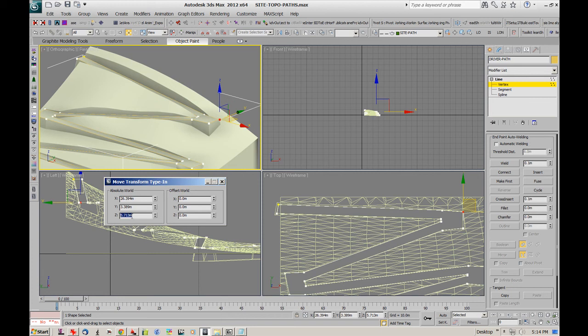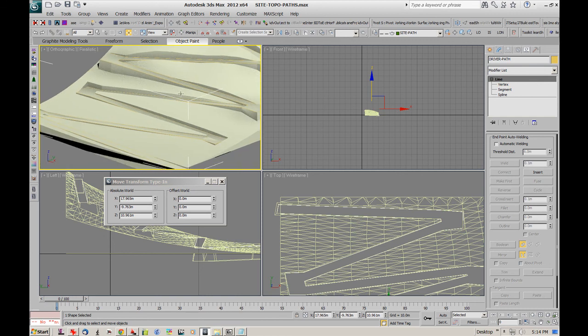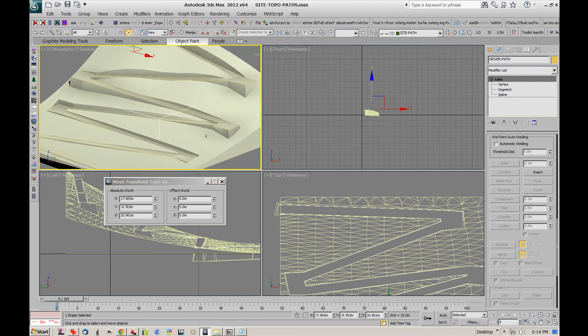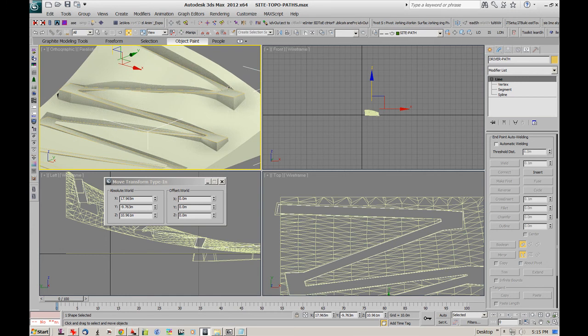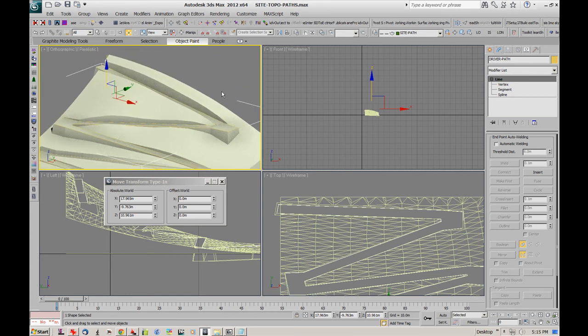So that's this guy, so you can move all of this landing down, offset at -0.2 or -0.3, and have quite a bit of control. I can go back up 0.5, and because it's procedural modeling, you can work your way back through the stack and it all updates nicely.